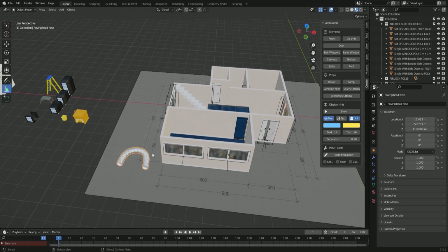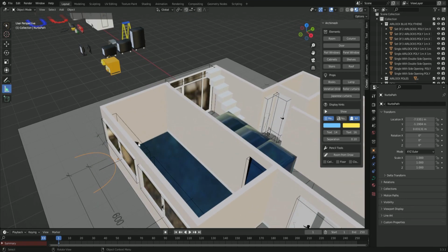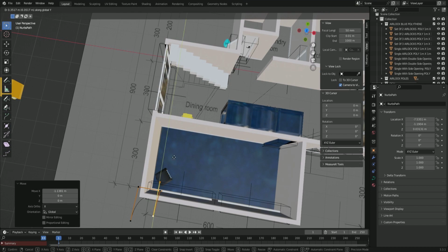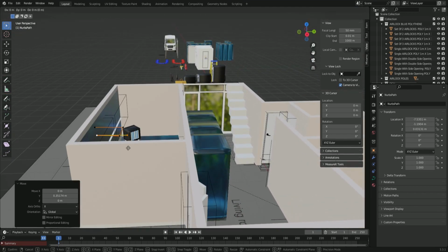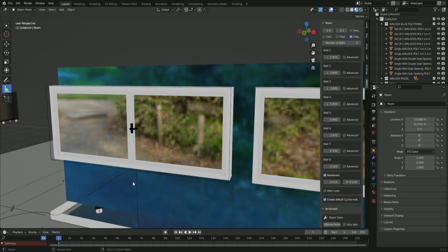I'm just going to show you how to use the ducting at the moment. We have got another video where I'll show you how to use the arrows and everything, which is the exact same way. Just tap the actual object itself, the ducting, tap hide H, and then you will see the curve that controls the shape of the ducting.